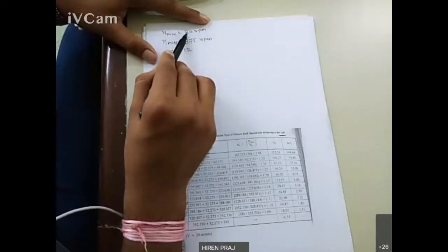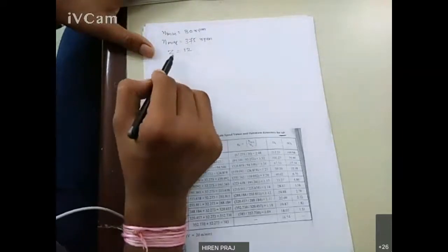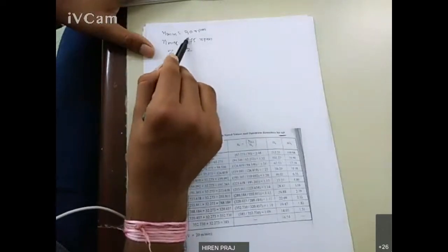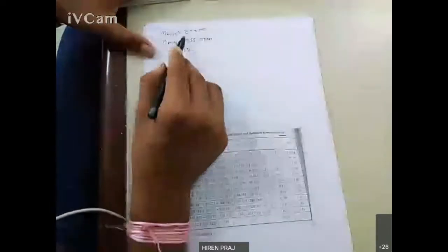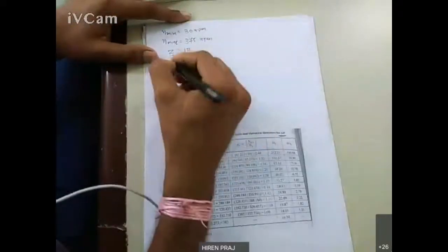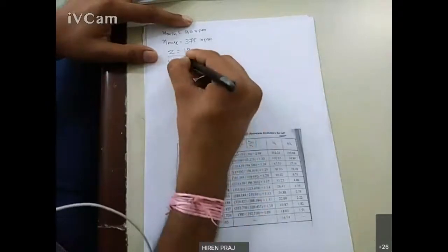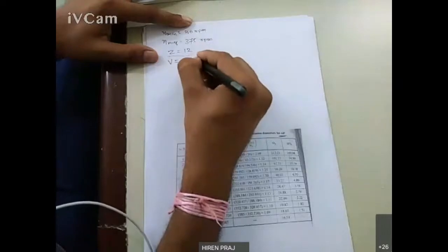30 is the minimum rpm available from gearbox, 375 is the maximum rpm available from gearbox, and we want total 12 speeds. So these two are covered, and within this range you require the remaining 10 speeds, so that you can achieve 12 speeds from gearbox, right? And suppose our material combination is such that the optimum cutting speed is 20 meter per minute.